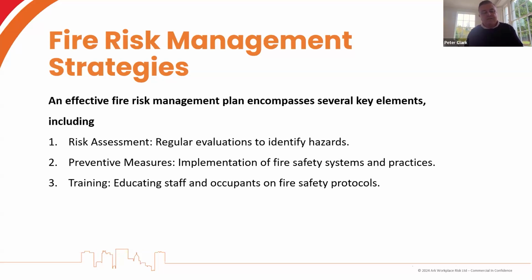Training. I can't stress enough, particularly now post-Grenfell, if you've got a building, whether it's a defend in place strategy or whether you've got a simultaneous or some form of evacuation to that building, if an alarm goes off and a sounder goes off and it's heard by occupants in the building, it's very unlikely that they're going to want to stay behind. So you've got to account for that.